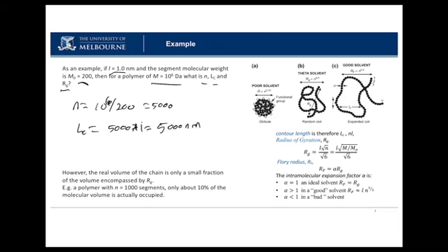So think about that as a polymer aspect ratio for a second. It's 1 nanometer wide and 5,000 nanometers long. So it's 5 microns long and only 1 nanometer wide. That's the aspect ratio we're physically talking about sometimes with a polymer. And if you do the calculation, you'll find RG using N or M naught over M naught, you can calculate it either way, is about 29 nanometers.